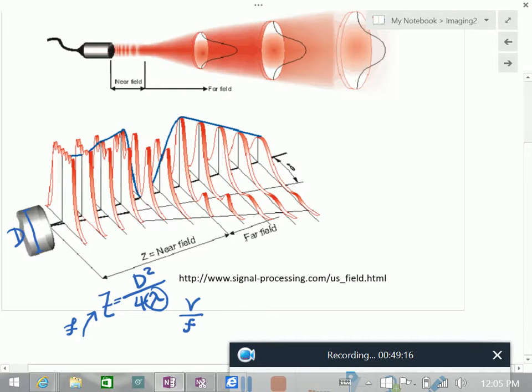But why do people not talk about it when they talk about the theory of wave propagation? Because all the load is considered a point, so we don't have to deal with any of that. This is when you go to the practice of using ultrasonic transducers. Because if the diameter goes towards 0, this zone really doesn't exist, right?